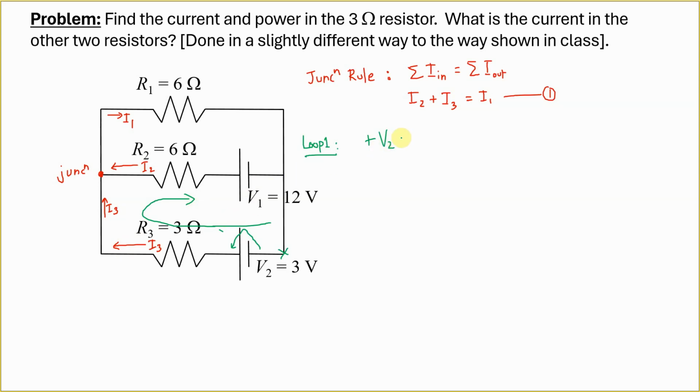So I end up with a negative sign in front of my potential drop across R3. Now, what is the potential drop across R3? By Ohm's law, it is I3 times R3. So minus I3 times R3. Okay. Now what else? So I go through R3, then I go through this wire. The wire has no resistance at all, so I just go to the junction, and then I turn this way. I'm now going in this direction through R2.